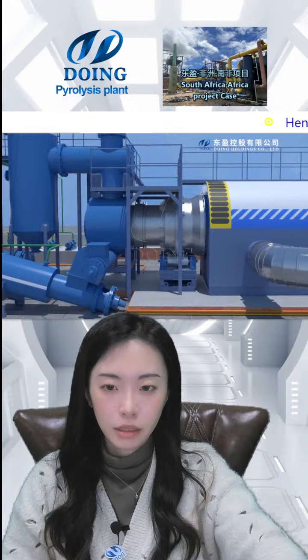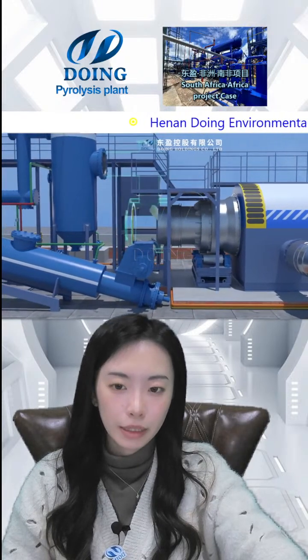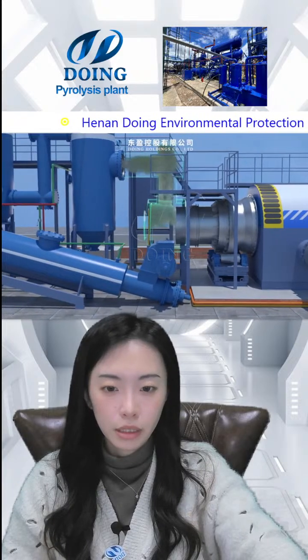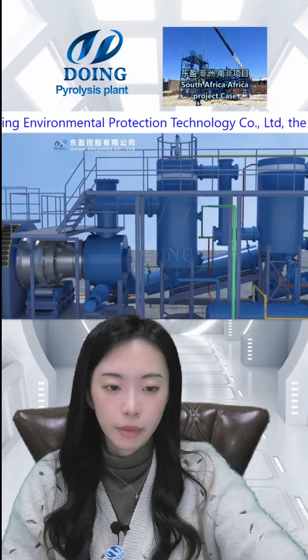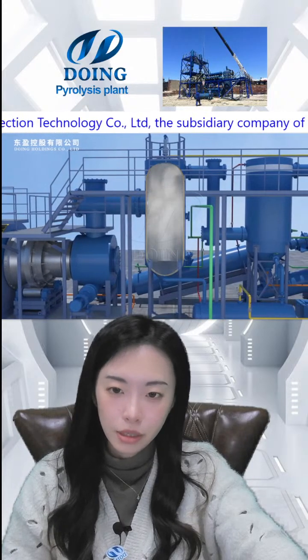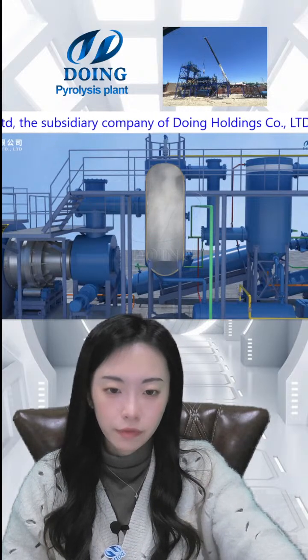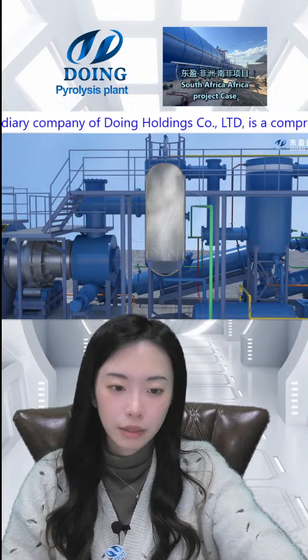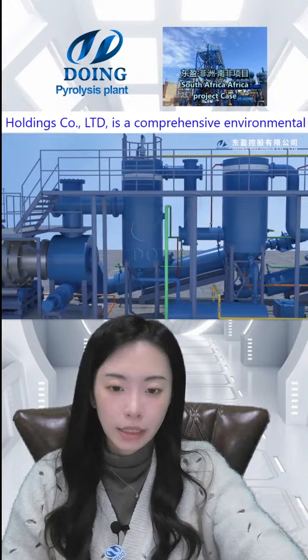And then this is the outlet of the gas and the carbon black. The green one is the fixed section. The gas enters the buffer tank upwards, and the carbon black falls back to the slag discharging step at the bottom. The buffer tank has 2 effects: first, to slow down the gas, and second, to precipitate the impurities.